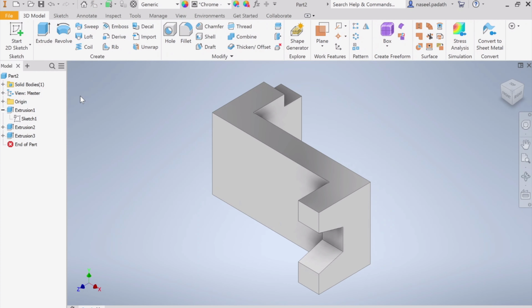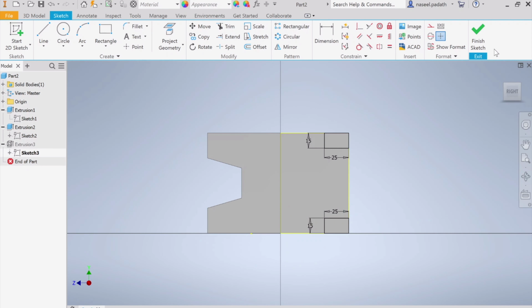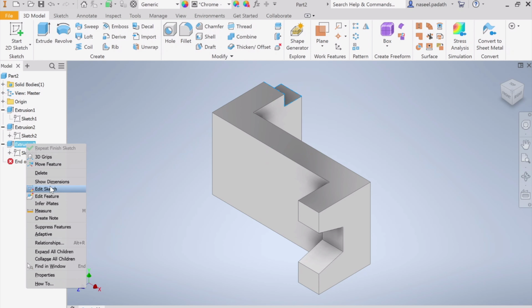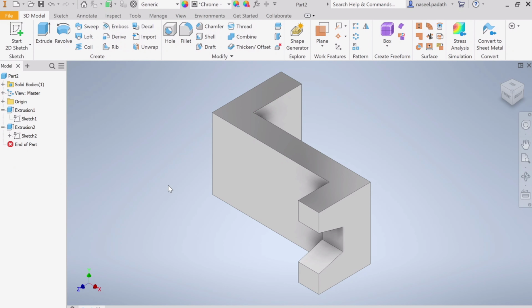Now return back. And similarly, you can see this is your second sketch. This is your second extrude. And this is your third sketch. And this is your last extrude. And this is how you can change. Double click, change it if you want, and return back as usual. So this is the model tree, very useful in order to manipulate or in order to change something. For example, I can simply choose this and delete this entire thing. So gone. So sometimes if you make mistake, you can change in that way. So this is how you can manage the entire process in Inventor.